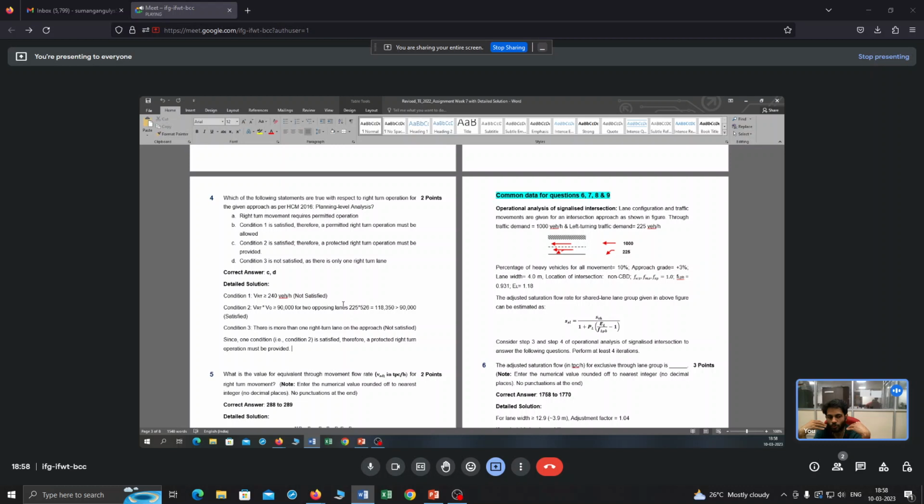But versus if you have two right turn lanes with similar traffic volume, there is a chance that vehicles will store there and will not create disturbance to these movements, right? So based on that, you may allow a permitted movement to be sufficient. You may not need a protected movement, because in the case of a protected movement, your movement will become unsafe and also will create chaos to the related right turn movements, so that may actually lead to difficulty.